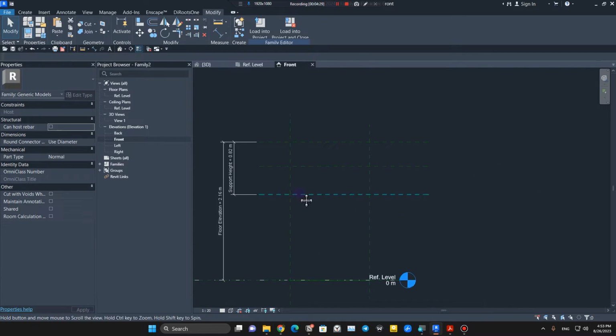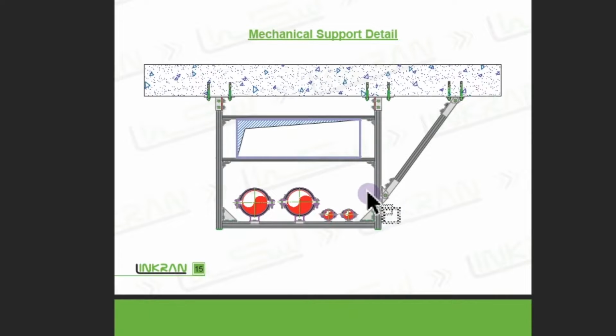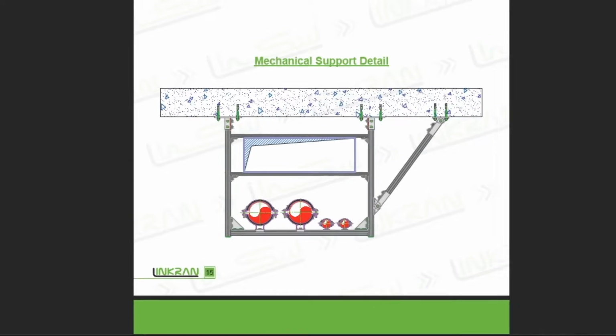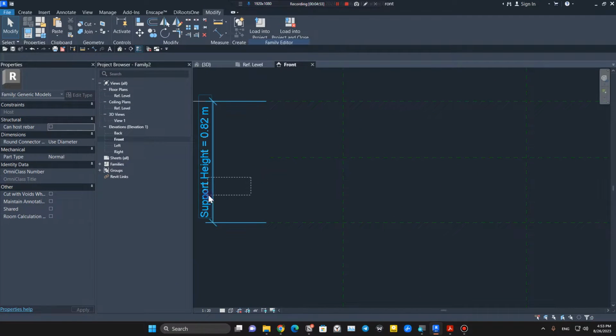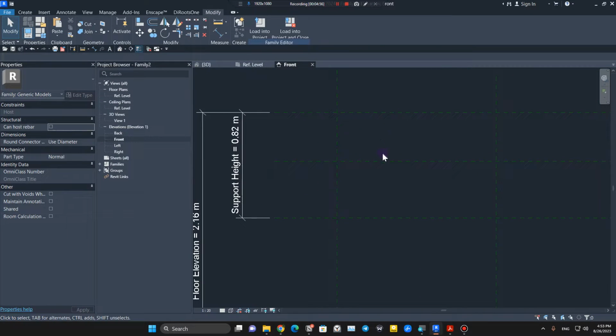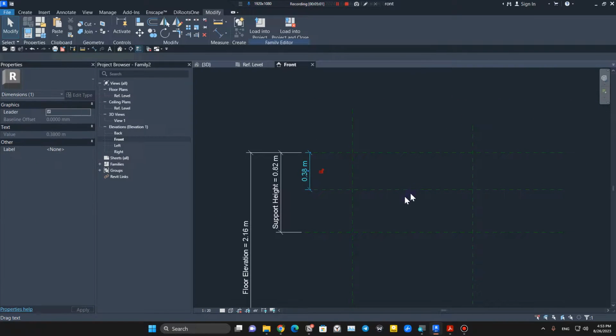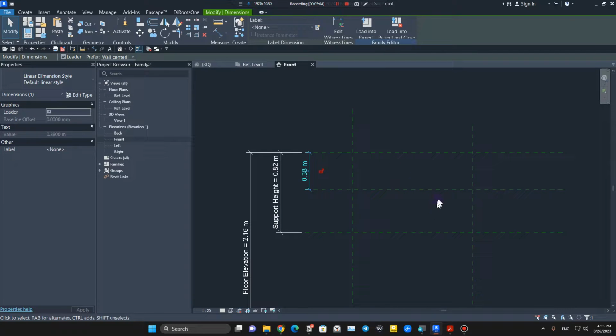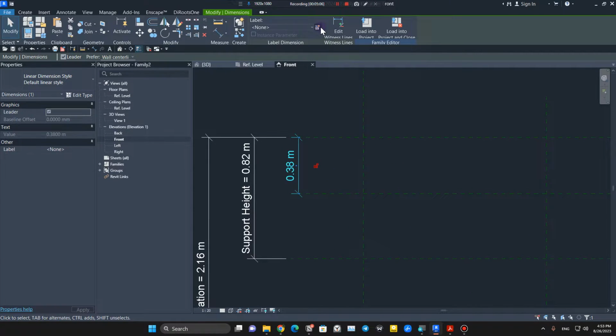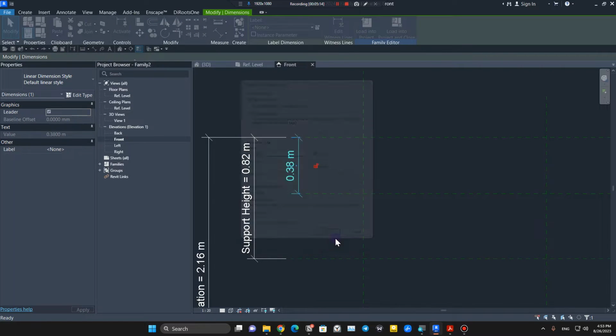Let's click on OK. And now if you go and look at the detail, you can see the upper part is a little bit smaller in here, and it's about maybe 40% or 30% of this dimension. I want to assign 40% to this part and 60% to this part. So for that, I need another dimension, which is going to be from here to here. Dimension again, let's assign this part to here too, and I'm going to name this part B1 and this part B2, so it's going to be B1 height, and click on OK.